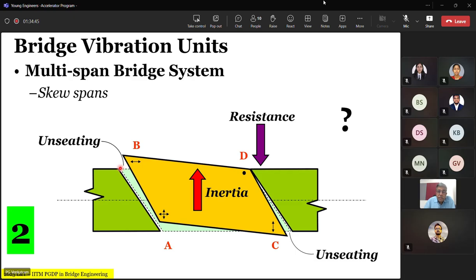Okay. So we are again discussing two things wherein you have the bearing articulation changed. Each one of them will lead to its own deformation characteristic. You have to be very careful about it when you're analyzing, and only then decide which is a better articulation. And the third possibility is polar radiating one, which is good. That's something that is important to choose when you're doing a skew span. But ideally avoid all skews.